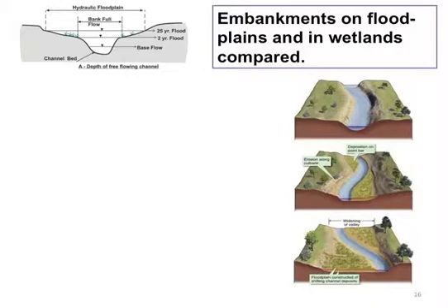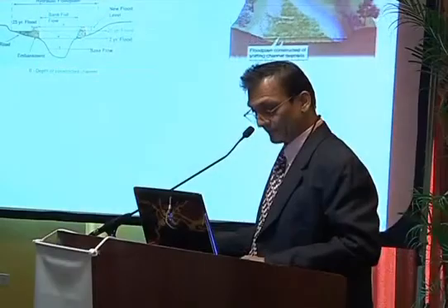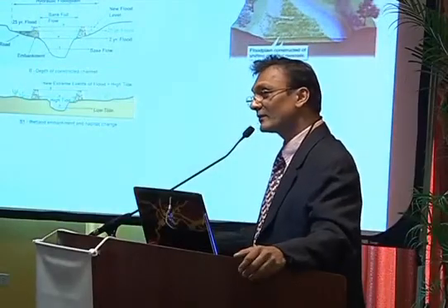The flood water that would have been there now has an increased elevation. So the 1 in 25 would have been here before the embankment and is now here. And if the embankment is not high enough for the particular flood return period, you will have disaster occurring where you expect it to be dry. In the case of the wetlands.